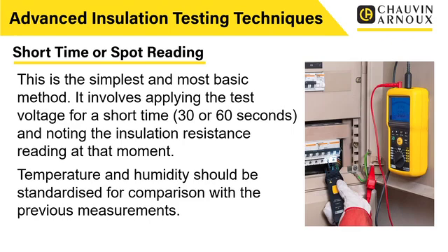Now, previously, when we were talking about doing spot measurements, we were pretty much doing that test there and then straight away. Now, we've learned that if we're talking about bigger insulation and higher test voltages, doing a spot test straight away isn't really a good idea, because the insulation resistance will change over time due to the capacitance and the absorption currents that need to neutralize.